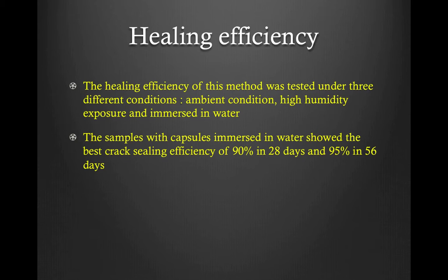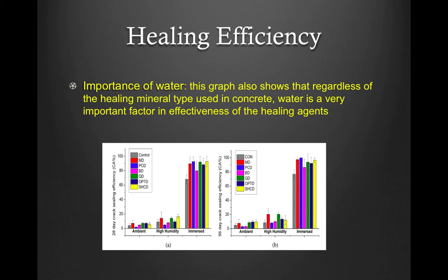The samples with capsules immersed in water showed the best crack sealing efficiency of 90% in 28 days and 95% in 56 days. This graph shows that regardless of the healing agent used in concrete, water is a very important factor in effectiveness of healing agents.